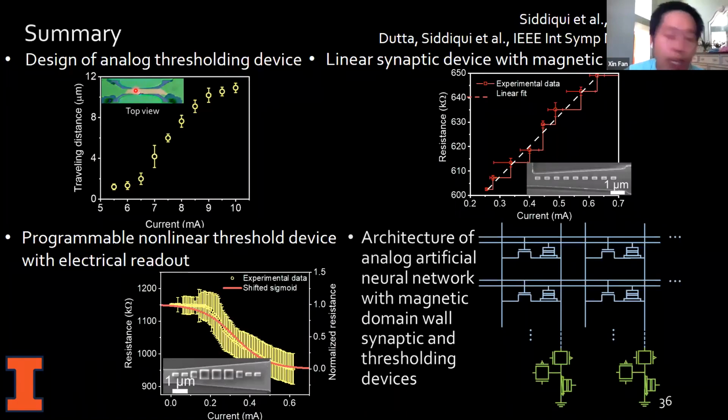And as you said, in principle, there can be material engineering to move the domain wall much faster. For example, I think there's a recent demonstration of cobalt gadolinium replacing the ferromagnet and moving even faster. So was all your energy consumption estimation based on platinum cobalt? When I'm talking about the energy consumption, those are for the digitized version of the Synaptic devices, and those are based on cobalt iron boron, which is definitely one of the worst systems, maybe, in terms of domain wall motion. I see. Good to know there's a lot of room to improve the energy efficiency.